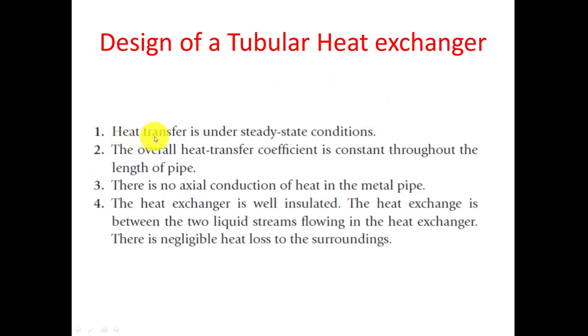Number one assumption is that heat transfer is under steady state conditions. Whenever we design a tubular heat exchanger, we assume that the heat transfer will be under steady state conditions. Second, the overall heat transfer coefficient is constant throughout the length of the pipe. Third, there is no axial conduction of heat in the metal pipe. Fourth, the heat exchanger is well insulated and the heat exchange is between the two liquid streams flowing in the heat exchanger, with negligible heat loss to the surroundings.